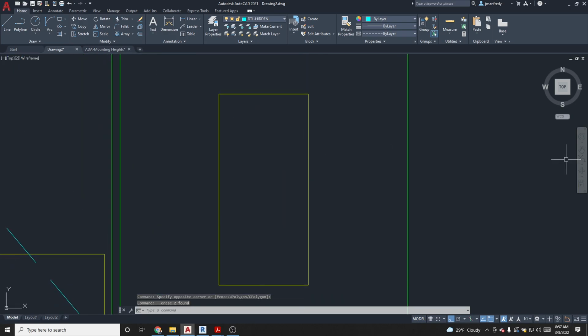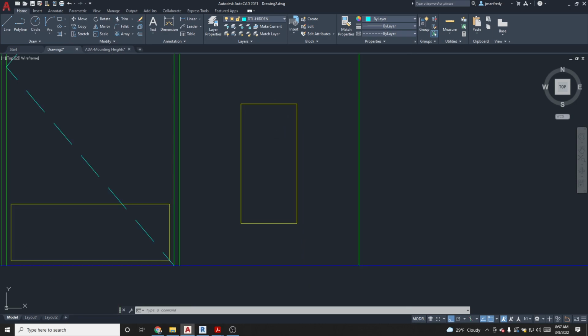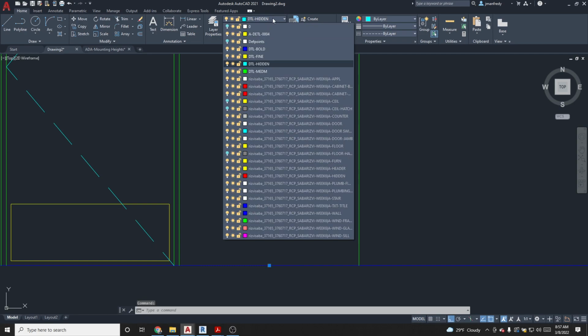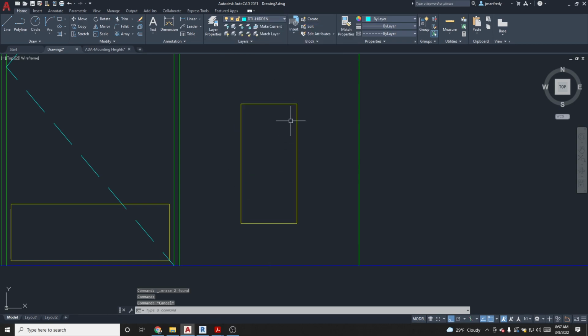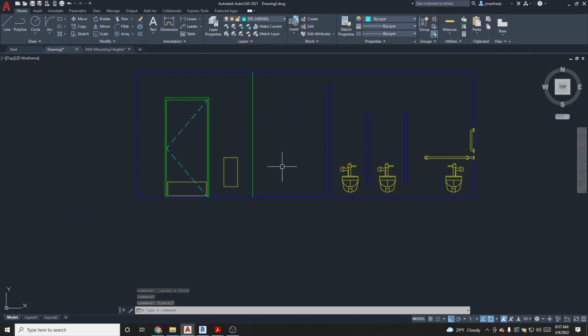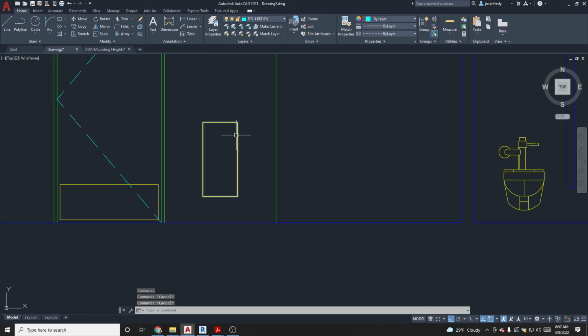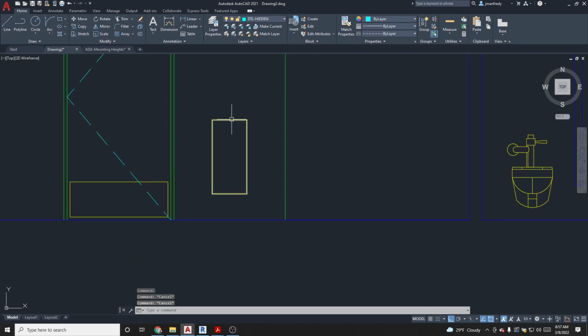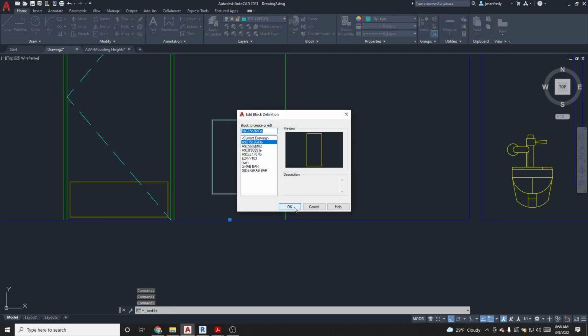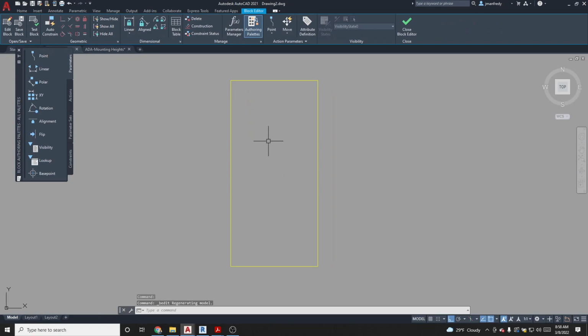Now, this has a little doorway here, so we'll go ahead and draw that. And this I will move to detail medium. And again, as we've done in the past, ideally these blocks should all be on layer 0. So come into here and move into layer 0. Then if I click here, you see it's layer 0. Then I can go into these blocks and update them. I can double click on these blocks and hit OK, and there's the drawing there.